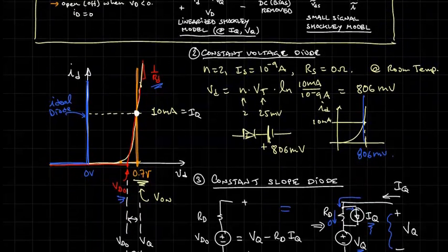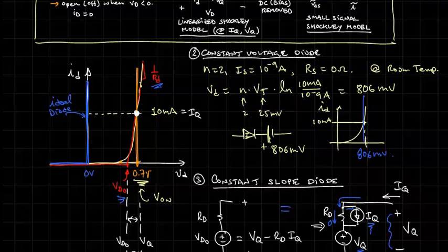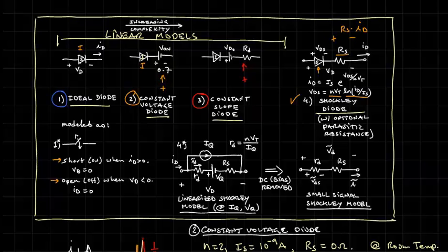Here's a diode IV curve on a linear scale. The diode curve is actually the yellow curve, and over traced on it are several of the models that we have been looking at. The one in red is the constant slope model. That's the model where there's an ideal diode followed by a constant voltage, followed by a series resistance.